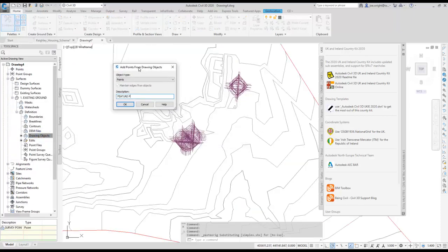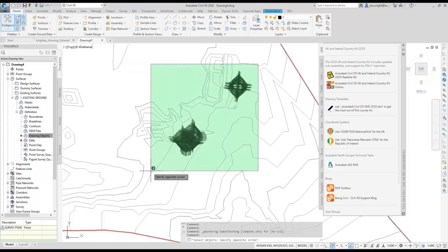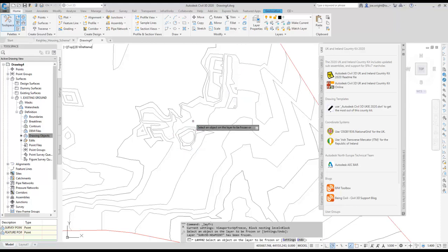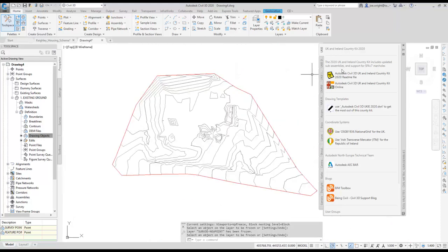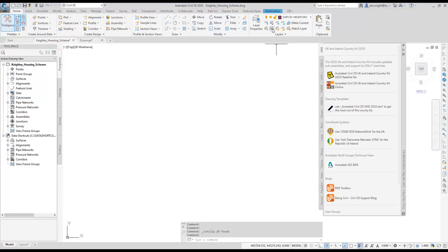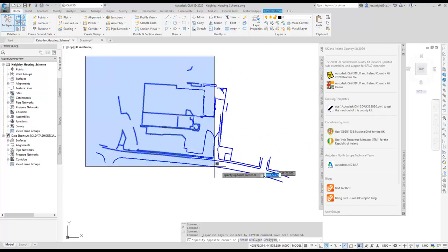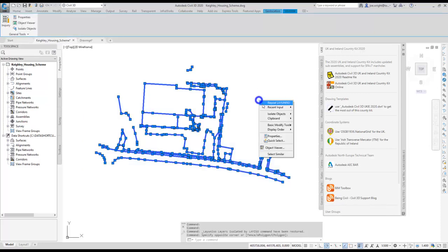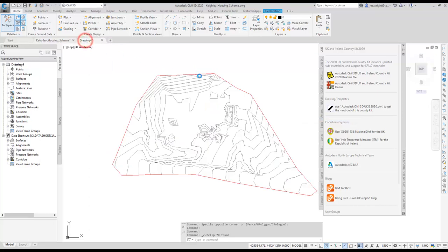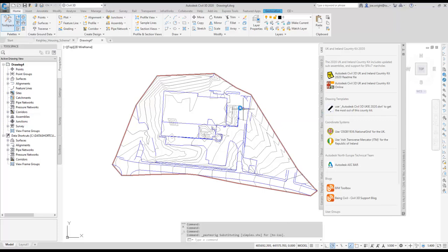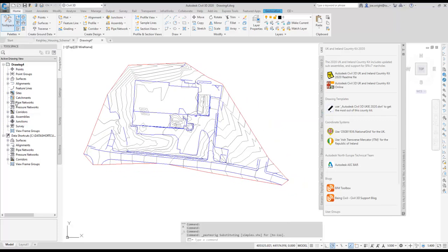Notice I've given them a different name, which means I can remove them from the surface if I choose to later on. I'll freeze these off too. And so back to the original topo drawing, and we can see what's left. This final geometry are lines and polylines representing feature edges. Maybe you should isolate these as we did before, but as they're all that's left, I'll simply cut them out and paste them in. Now I can add these to the surface. These will be break lines.